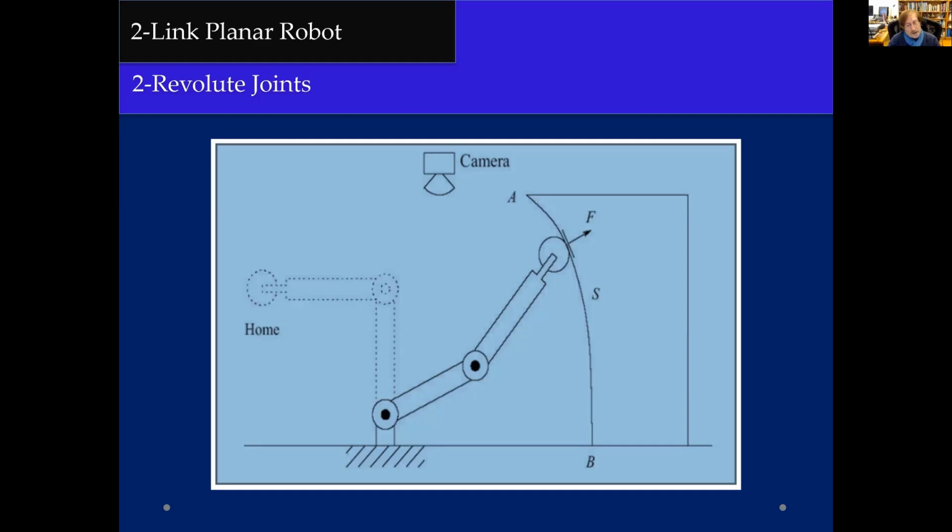For a more complicated case, if there was a third dimension, if I was asking the robot to carry out this task in the third dimension as well, would this robot be sufficient? No, because then the number of elementary motions would be increased to 3. Then I would need a 3 degree of freedom robot, and I would need at least 3 joints. So I am carefully saying, I'm not saying 3 joints, but at least 3 joints.